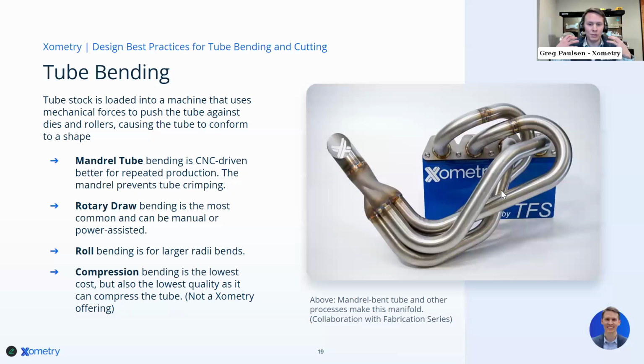And so you're consolidating this need for welding. You're creating a more consistent and repeatable experience. Going from 1 to 5 gets cheaper and cheaper every single time, versus keeping that same overhead for every single weld you're doing on this. And you get a more consistent product using CNC driven design with mandrel tube bending. We would also need a manual review, but from roll bending.